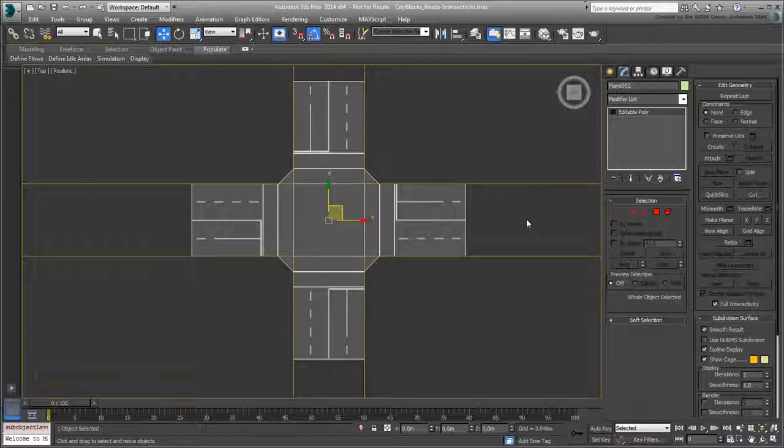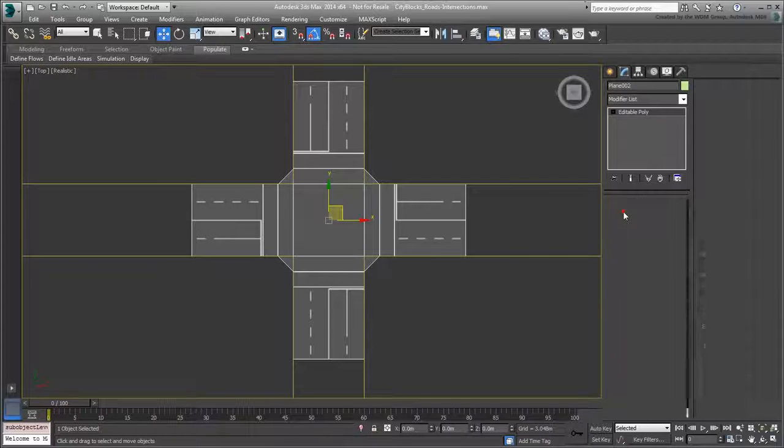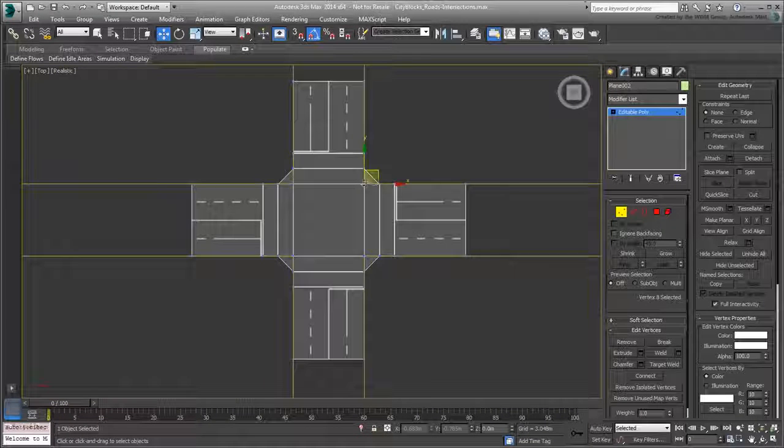You're almost ready to move on to the next movie, but a couple of things remain. First, go into vertex mode and note that vertices are not welded yet, even though they are in the right place, considering how you created the objects. Select all vertices and note that there are 64 selected, where there should be quite a smaller number. Click the Weld button to fix that problem, and end up with 28 vertices instead of 64. And exit vertex mode when done.